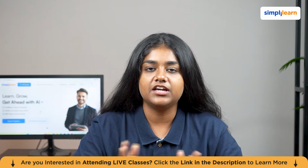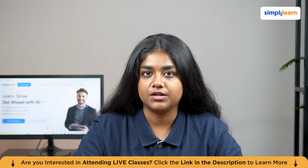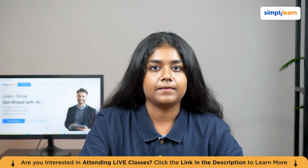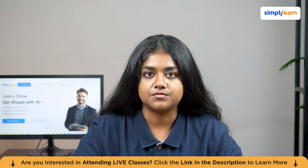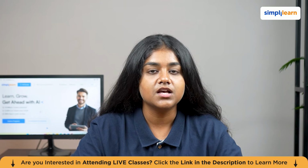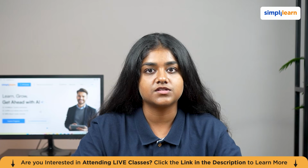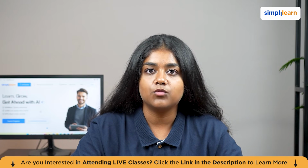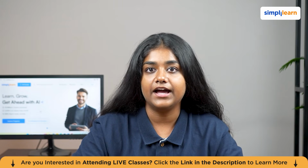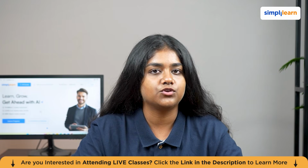So now let's do a brief recap of what we have covered. In this course, we covered the foundational concepts of bias and variability all the way through sophisticated ANOVA-based Gage R&R and Kappa statistics for attribute systems. In Module 1, we introduced the foundations of MSA: what a measurement system is, why data quality matters, and how measurement error impacts product decisions, process control, and hypothesis testing. In Module 2, we covered bias, the systematic error in the measurement system, how to detect and test it using reference values, and how to evaluate its acceptability relative to tolerance.